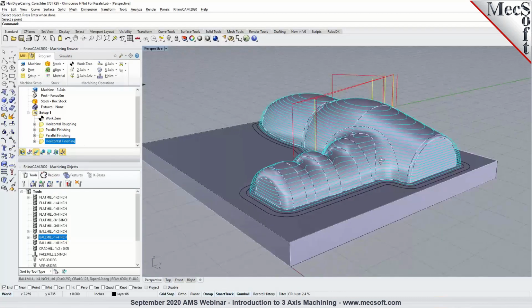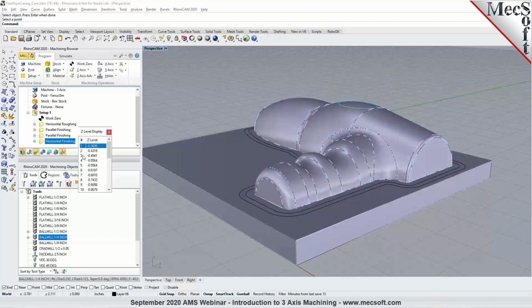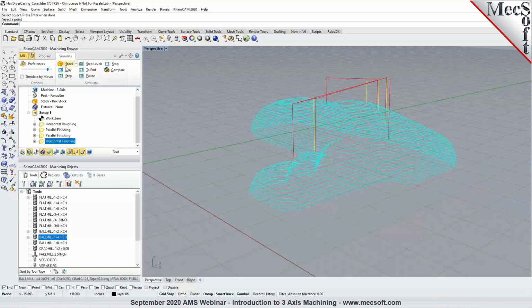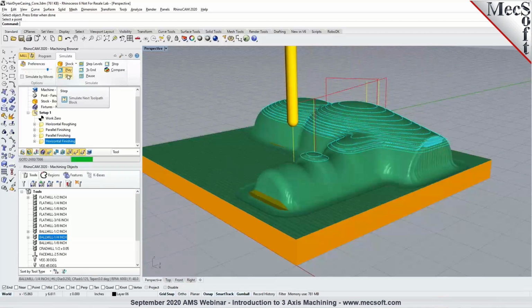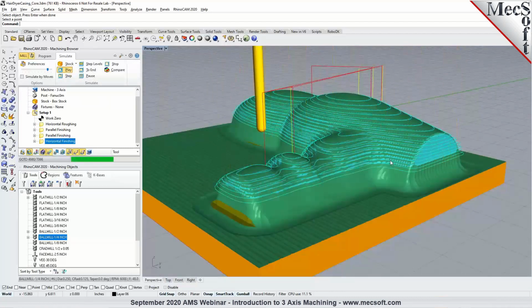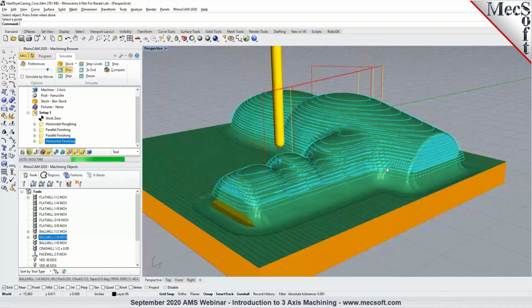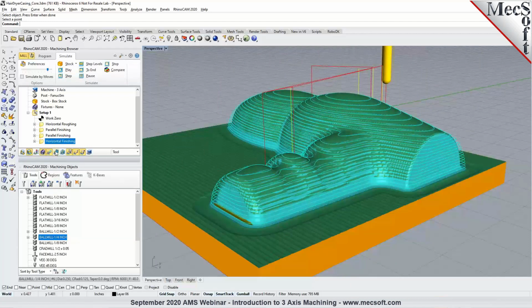So you're noticing here the toolpath generator is known as horizontal, or also called Z-level finishing, where it's generated in constant Z levels. I'm stepping through the Z-level display, and as you can see, the toolpath displays in levels. So this is a good technique to program steep areas in your 3D models, and this will go ahead and take care of cleaning up all of these scalloping that were left in the steeper sections on this particular core mold.